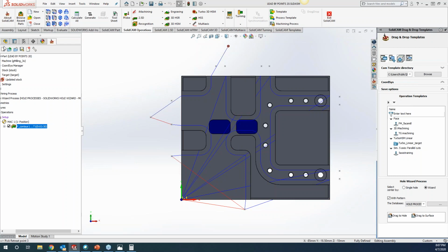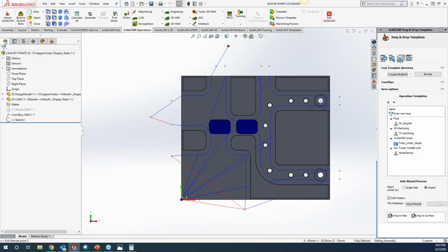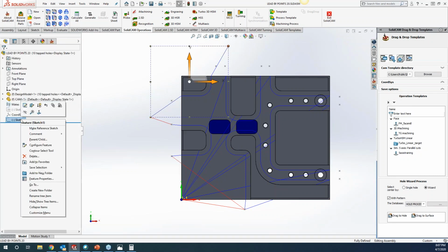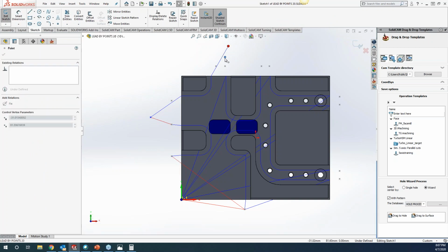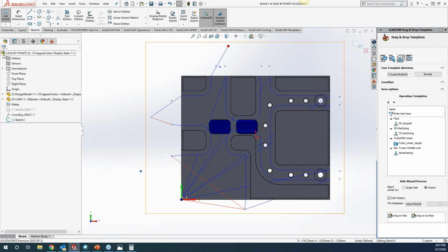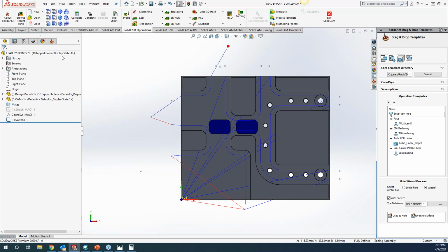So now, if I go over to my SolidWorks and come in here and edit my sketch, and maybe let's just make this down farther in between these other 2 points right there, as well as this point right here. Let's go way off so we can see it very well, okay? Go ahead and hit your green check mark and exit my sketch here.